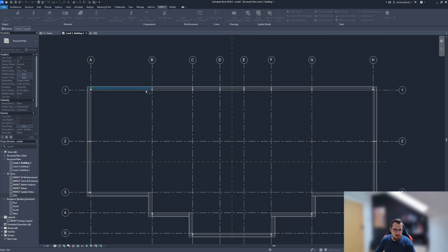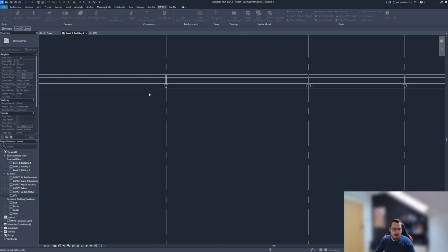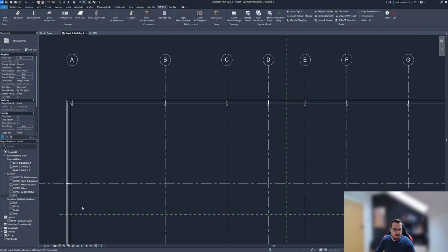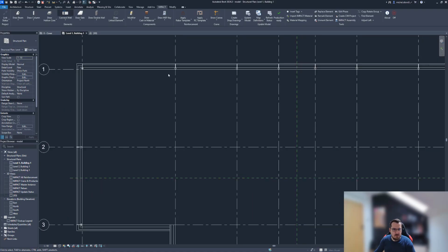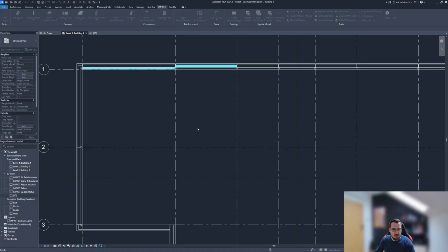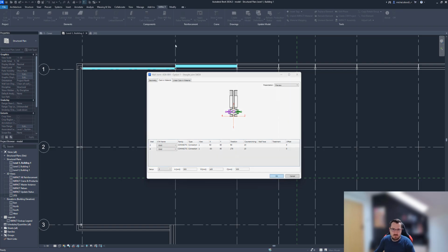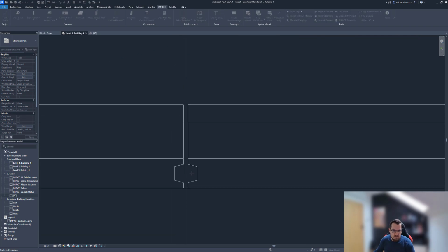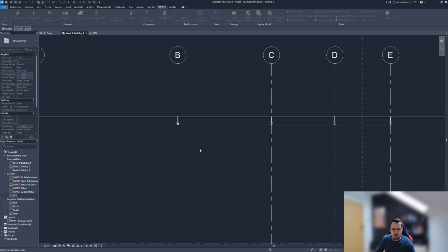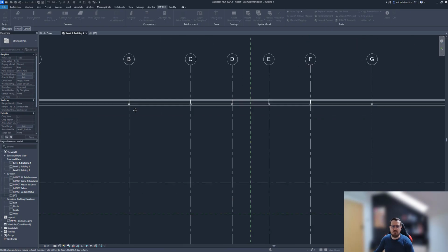Of course, that's not the only type of connection that we have defined in Impact. For example, I'm just going to cancel out of that and get the connection again. Select these two types of connection, and we get, for example, a proposition like this to connect those two walls. And I'm gonna set the default settings as well. With this one, you just have to also select the origin point, so you could potentially move that connection point left, right, however long you want it along the length of those two walls.